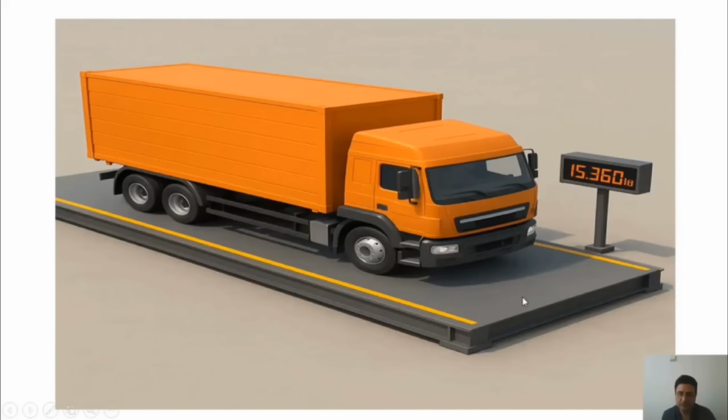One of the most important uses of weighing equipment in industry is in weigh bridges, which we can use to weigh vehicles. Now, this vehicle could be a passenger car, or it could be a heavy vehicle like the one you see in this picture. For example, a truck. We usually use these weigh bridges to weigh vehicles, and depending on the specific size of the weigh bridge, we can use either 6 or 8 load cells. The load cells are connected together and ultimately connected to a display, where we can see the weight of the vehicle.